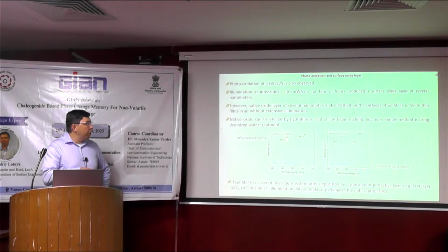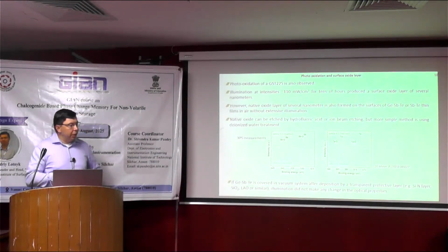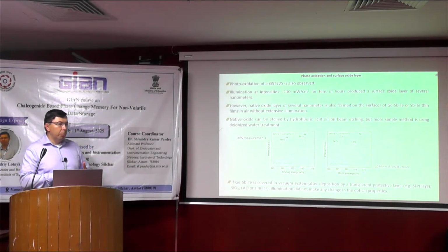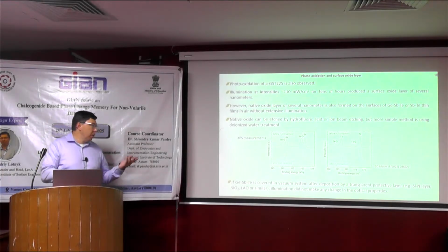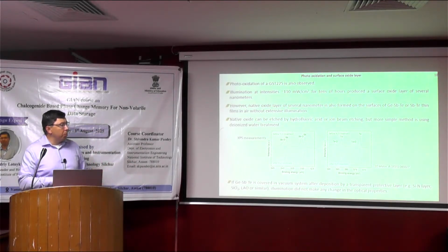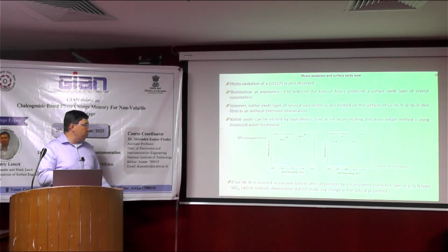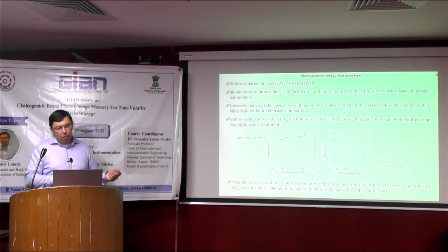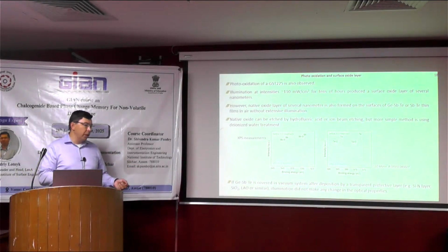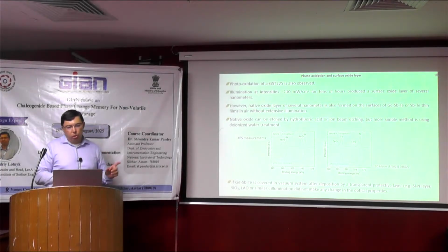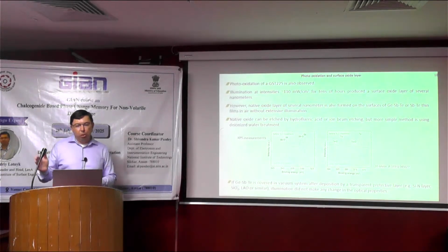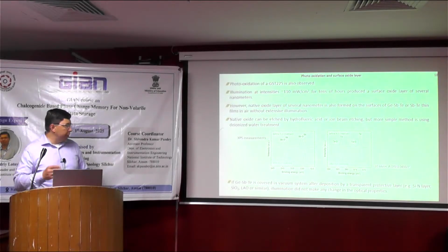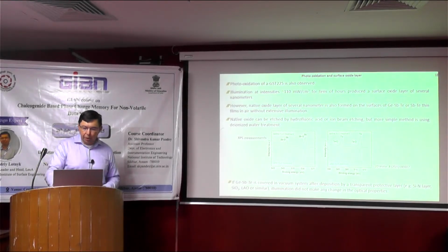Another way to overcome this oxide layer is to deposit a protective layer directly in your system. If you want to use optical measurements, you deposit materials like silicon nitride, silicon oxide, or lanthanum oxide, or similar optically transparent materials, which do not influence the properties of your system much. Or, if you have the possibility, you deposit contacts for electrical measurements directly in the chamber.